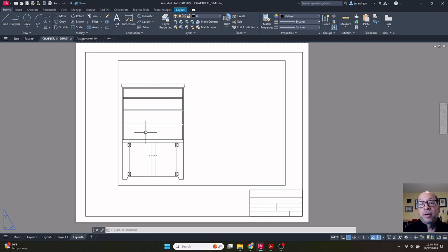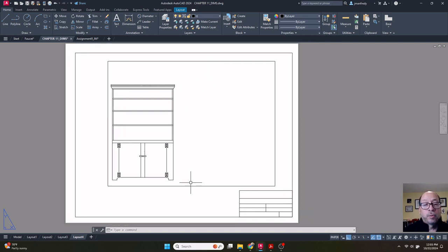So that drawing cannot change scale because it has measurements that we're going to include and we'll draw them in model space. And this box has to be locked in order to do that because the text we're using is annotative. Annotative requires to have a view that has a scale assigned to it. And ideally, it's locked. So accidentally, you don't zoom in and out of the drawing and lose your dimensions because they will disappear if the scale is not what AutoCAD is expecting in terms of the formatting we set up at the beginning here. So this has a certain scale assigned to it.